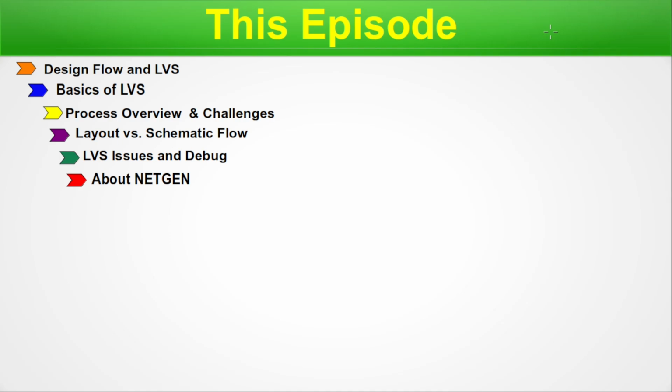In this episode, along with the basics of LVS, we will also discuss the basics of NETGEN. After that, the significance of the Setupfile. This Setupfile is absolutely connected with running the NETGEN tool. We will discuss its importance and what it means. Next, what is a valid file name? Whenever we encounter a NETGEN command, we will see that a valid file name is used in many places. We will try to understand what a valid file name is with respect to NETGEN.